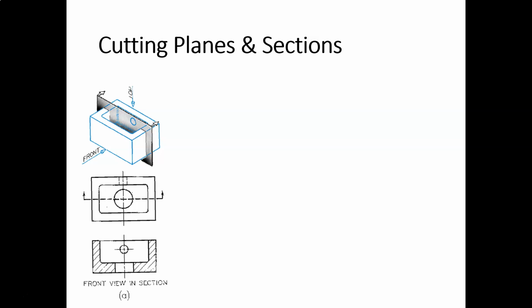Here we have, this is very similar to what I just showed you. Cutting plane separating the object in half. Here you can see the cutting plane line is in the top view, generating a front view section, front view full section.